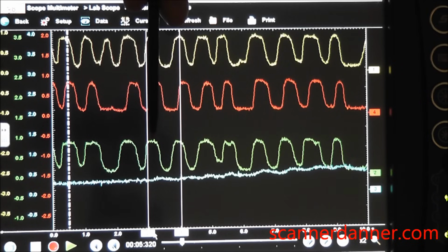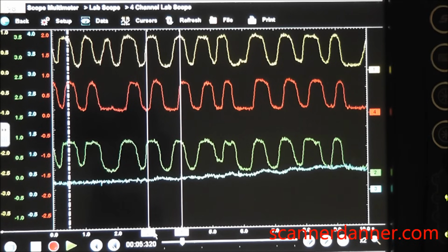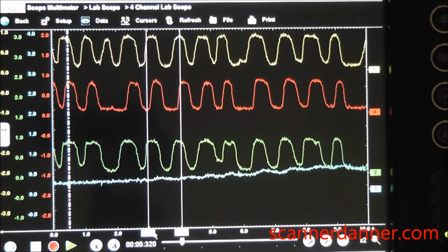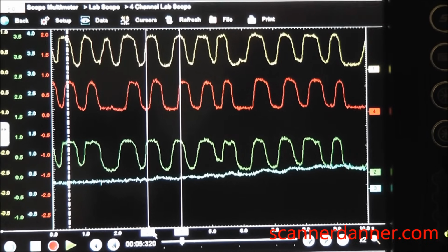I have just over a 1 hertz signal on my bank 2 upstream O2, so I don't see any issue with the O2. That would be something to consider. I've heard sluggish O2s, a sluggish upstream can be a factor too. I've never seen that. Generally speaking, I don't see any oxygen sensor trouble codes. I only have a CAT code. I don't even hesitate with it anymore. Pretty much needs a CAT, a factory CAT. Just make sure the engine's running good.